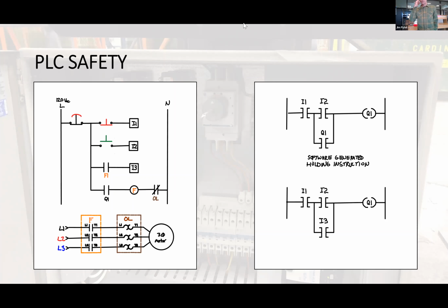There's a much, much better, much safer way, and it is what is done in the field. I much prefer individuals use what they're going to see in the field, which is to actually use real world feedback. Where is the real world field feedback? It's on input 3. That's the F1 auxiliary contact associated with the F contactor. You must have an understanding of whether that contactor is open or closed. So the motor starts, and the F contactor closes.